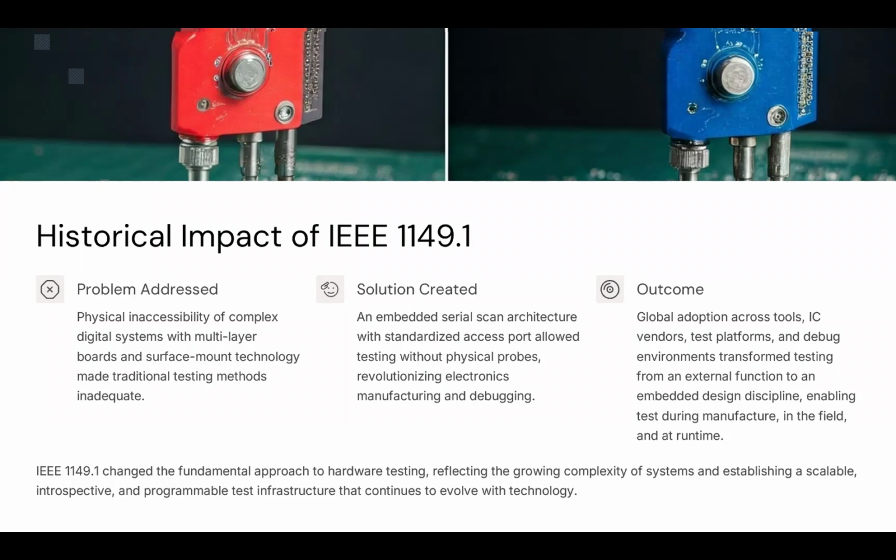So we needed a new method to solve that, and its solution was created by developing IEEE 1149.1, which introduced a scan structure embedded inside the digital ICs. So it's a new paradigm of testing. It's not an external testing, it's actually embedded inside the ICs. Normally the designer places flip-flops and logic cells at each input output pin, and they form a shift register chain. We are going to call it a boundary scan register, which allows each pin to be observed and controlled serially through a small number of test pins.